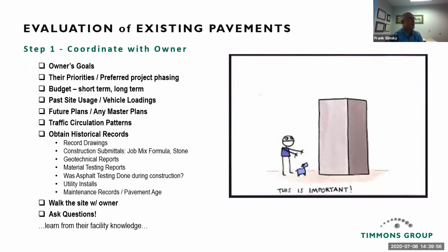So step 1, coordinate with the owner. That's when you find out what your owner's goals are, their priorities, their preferred project phasing, their budget, short-term or long-term, past site usage, vehicle loadings, future plans, any master plans available, traffic circulation patterns, and obtain their historical records, record drawings, construction submittals, job mix formula, stone, geotechnical reports, material testing reports.